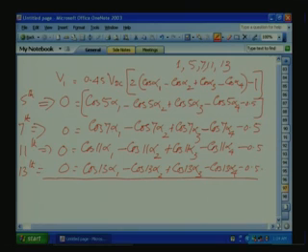and we have to compute alpha 1, alpha 2, alpha 3, then store this pattern in a memory and output. In some cases, suppose we want to eliminate the next harmonics also, that is the 17th and 19th, then the number of equations will be more.